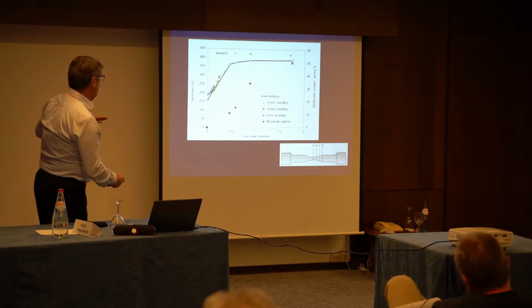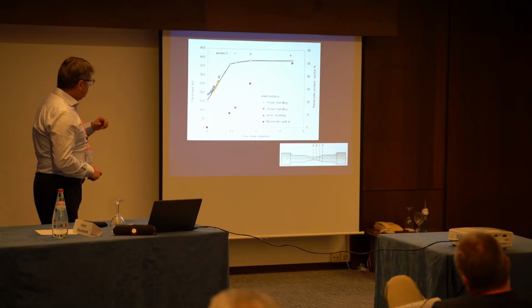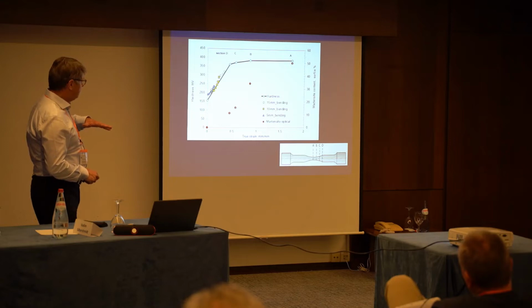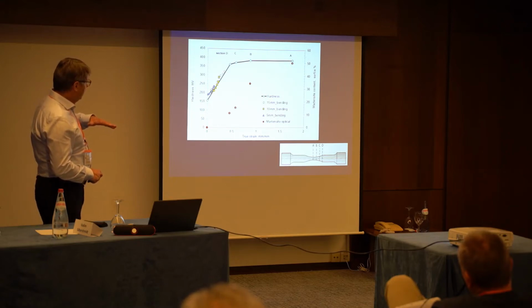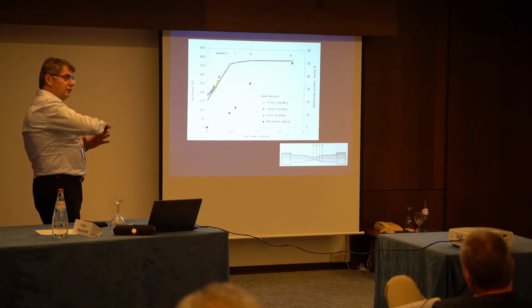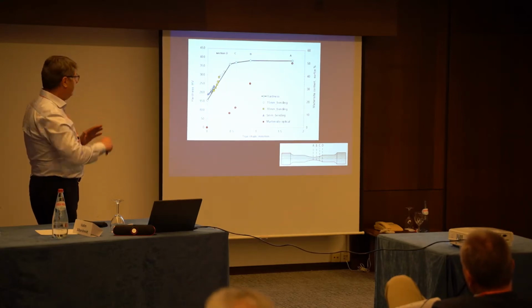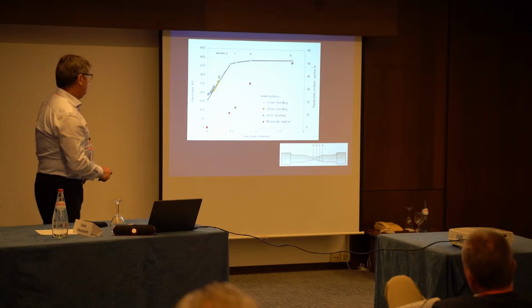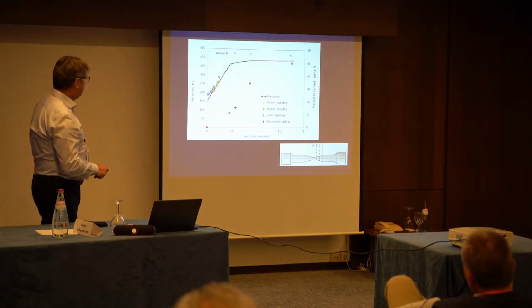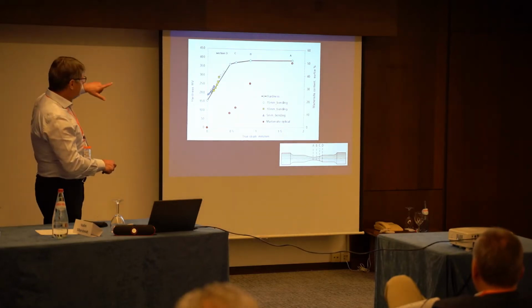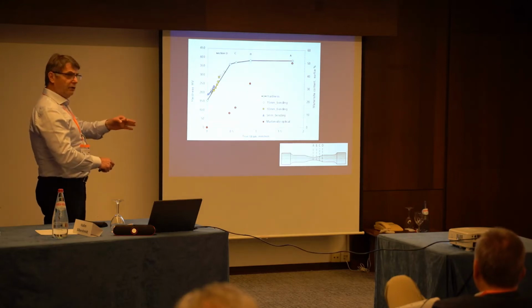So the second thing is now we want to put this hardness, and here it is for 5 millimeters bending in these blue points, for 10 millimeters bending is yellow, and white rounds are for 15 millimeters bending. Actually, everything is on one line. It only depends on the stage how far you are going with this bending. So it is always testing the same material and the same behavior. And also here you can see that suddenly after a strain of about 50%, 0.5, you have one plateau. And this is what we measure on these samples, on which we made the metallographic analysis.